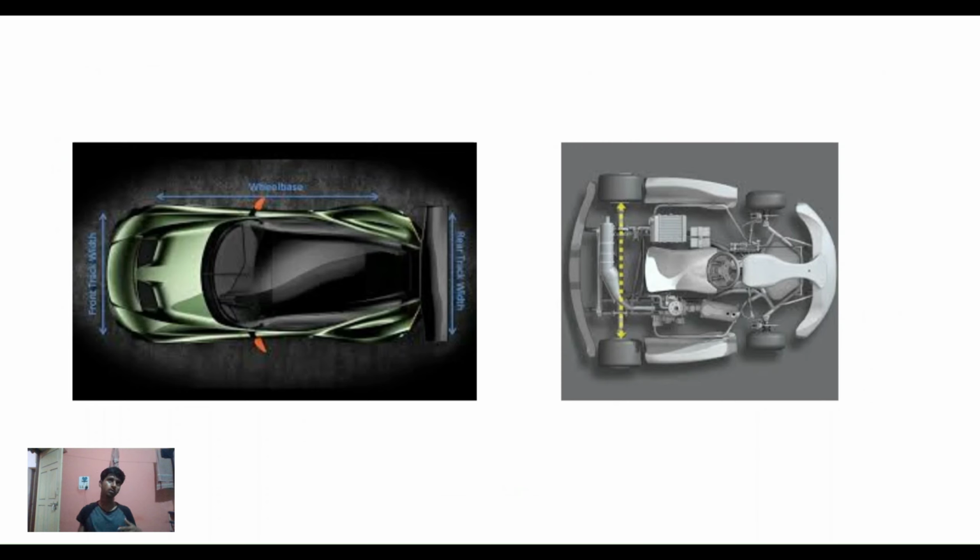Now, you might ask, okay, fine, let's use a larger track width, but how does it help? Think about the torque or the rolling force which is acting on the vehicle here. During a tight turn maneuver, the centrifugal force is providing a rolling force or a torque along the outer wheel, about the CG, right?